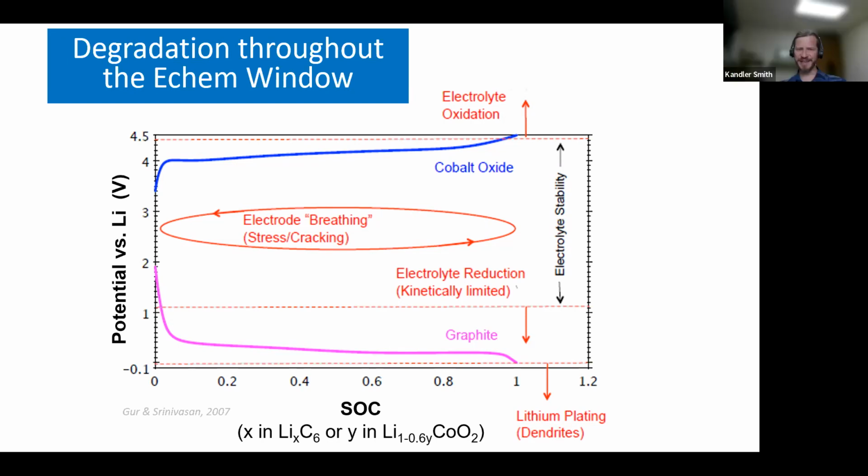It seems okay as a simplification step, but I'd like to see more work there as well. Oftentimes we will run calendar aging tests where you're almost running 0 cycles on the battery, and fully accelerated cycling tests where you're running as many cycles as you possibly can in a day. Then if we can afford to, we'll put in a couple mixed aging cases where we're doing maybe 50-50 cycling and rest on the cell, or something that gets a little bit closer to the actual system. And generally the models hold up pretty well with that untested condition.